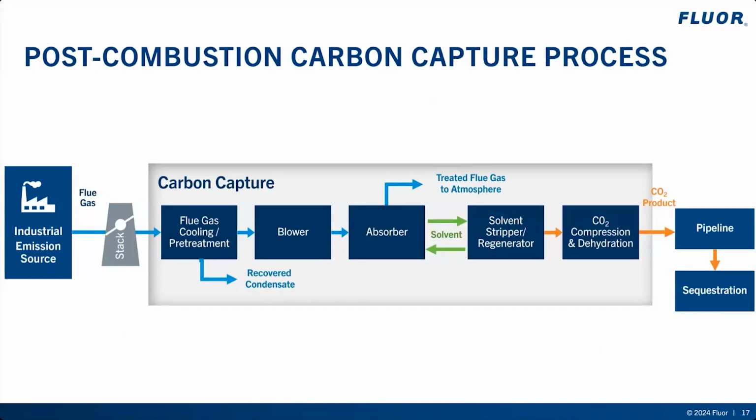The condensed water from the flue gas is relatively clean from most flue gas sources, and the collected water can be recycled and reused in both the carbon capture plant and base facility water systems. A blower is located either upstream or downstream of the flue gas cooling step to overcome the pressure drop of the flue gas handling system.